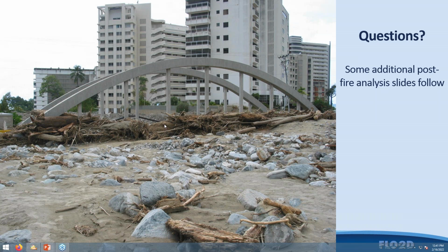So for lahars, the best thing you could do is to have the viscosity and yield stress relationships, as they might vary from the mudflow relationships. On the other hand, if you don't have the ability to do a viscometer laboratory analysis of the lahar, just use the most viscous of the sediment mudflow deposits that I showed you last week. And typically that's Glenwood number 4, but you can do your own analysis of the samples.